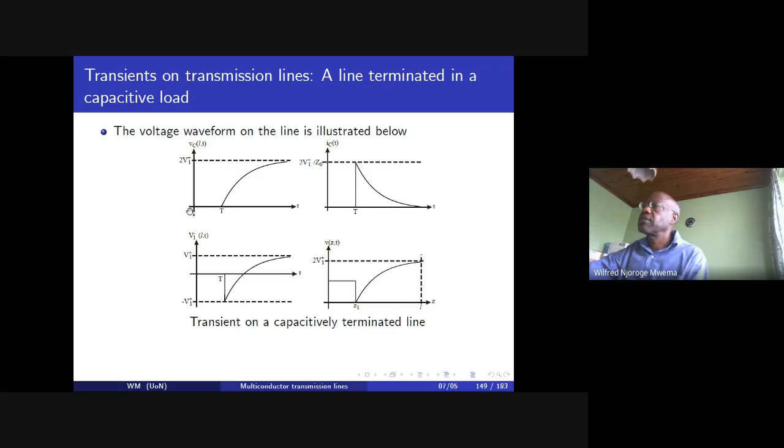Now, this, of course, follows what physics says, that the voltage across a capacitor cannot instantaneously rise from zero, and therefore we see that this also conforms to your circuit theory. And you can see that the current will first of all shoot up, because if the capacitor is uncharged, it will appear as a short circuit initially, and then as it starts getting charged, it starts going to an open circuit, and the current should then go to zero.